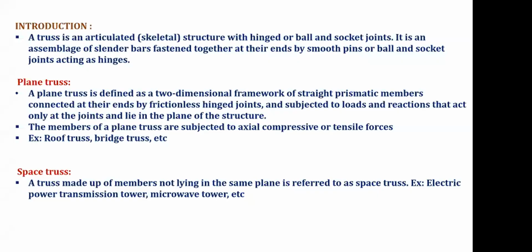As per the introduction and this very simple definition, a truss is connected inclined and straight members joined as pin jointed trusses. The best shape is the triangular. There is a classification: plane and space. Plane has 2D problems in XY, and space has three-dimensional objects. At UG level, we will solve only 2D problems.